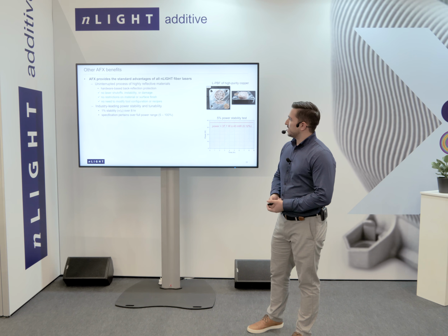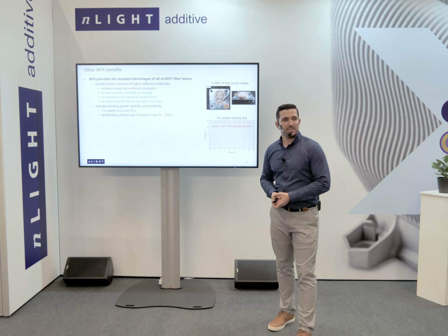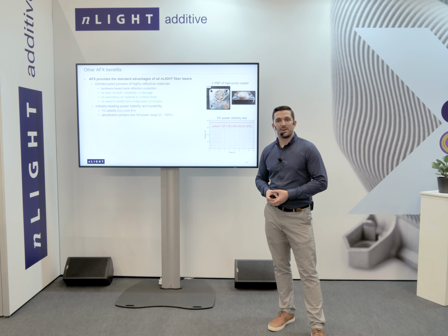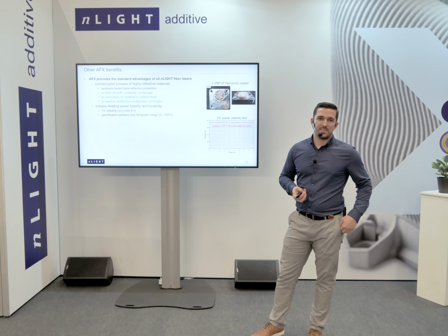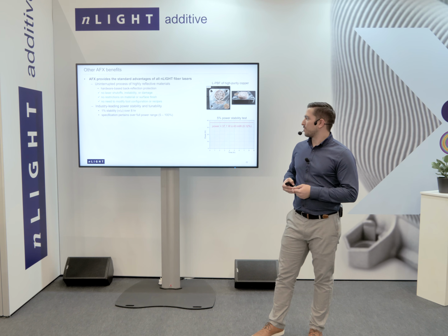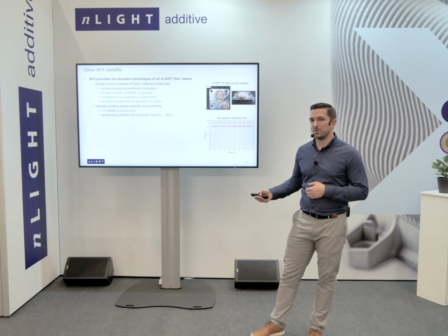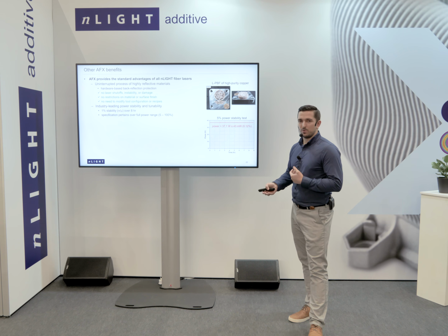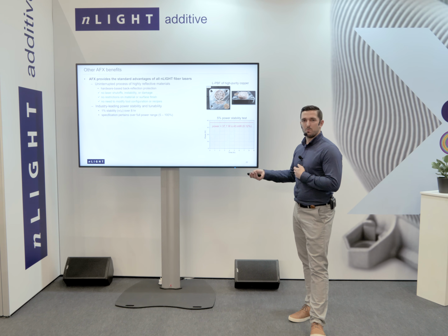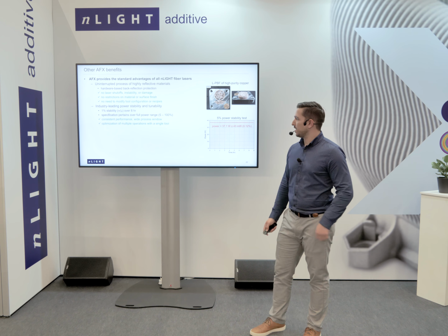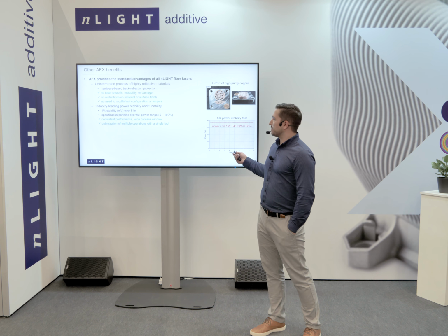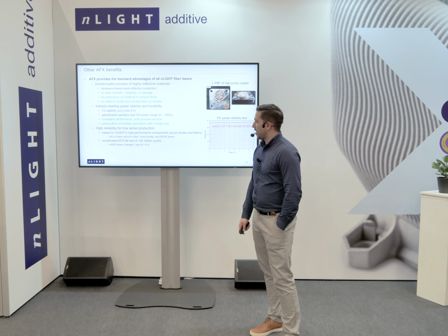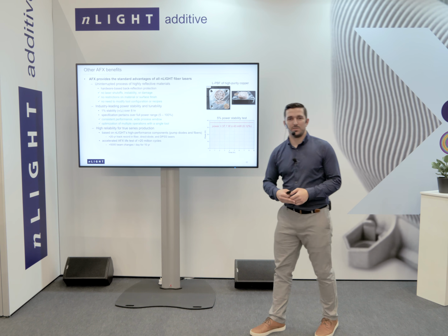We also provide industry-leading power stability and tunability, which is very important for additive manufacturing. We have a 1% power stability spec that is uniquely applied for our full power range. That means a 1 kilowatt laser being run at 5%, 50 watts, is just as stable as it would be at 1 kilowatt. It means that no matter what your process window is or your power level, you'll get the same consistent results.